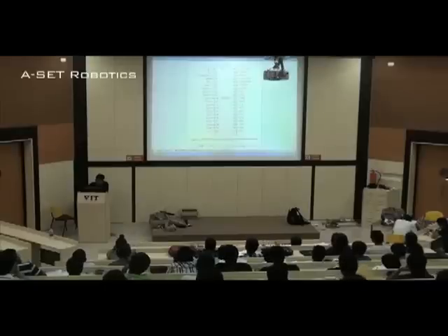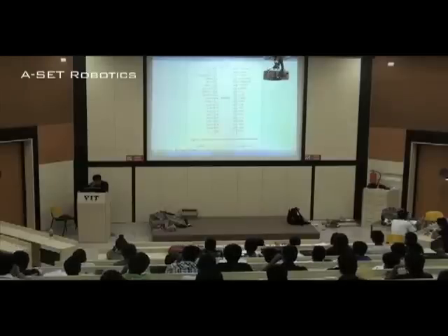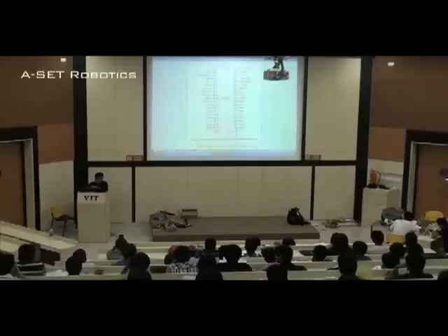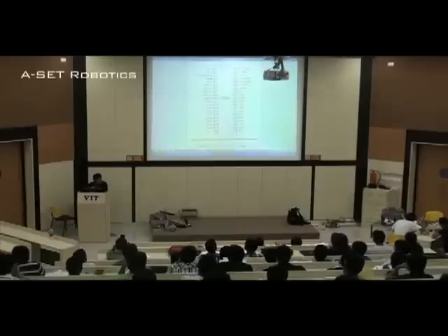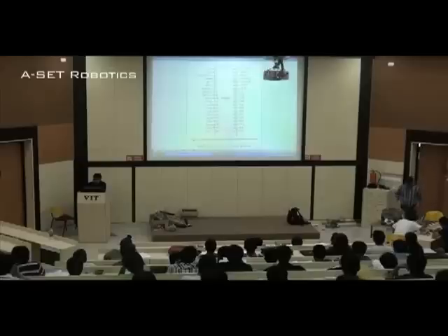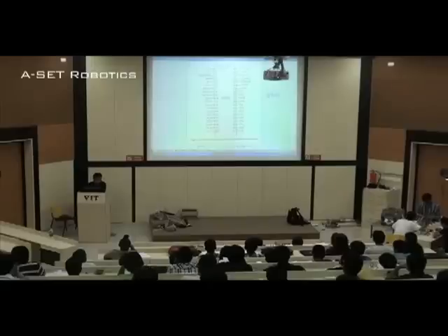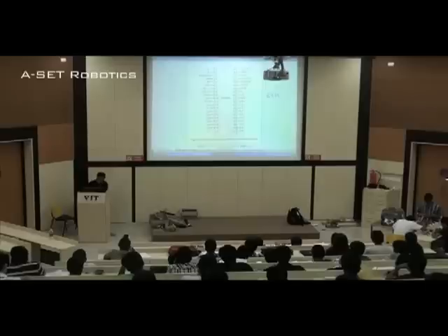Now AD0 to AD7. When we are talking about the data, how much data would get inside at a point of time? 8 bits. So you need 8 pins to use that port, right? 8 bits, 8 pins. Now one more thing that I have not told you: the address that it can actually handle is 64K. 64,000 memory locations can be accessed by this microprocessor. Why?